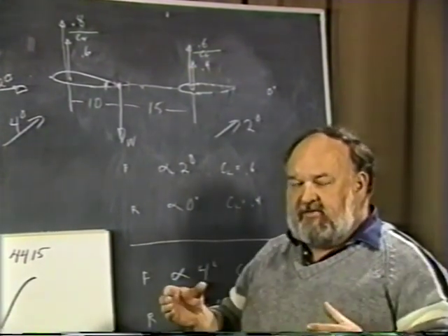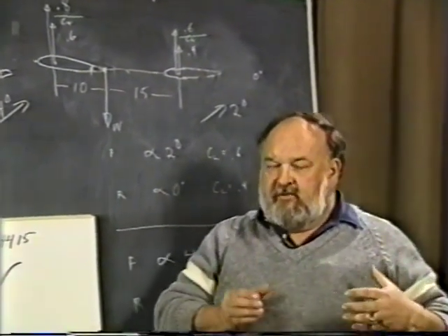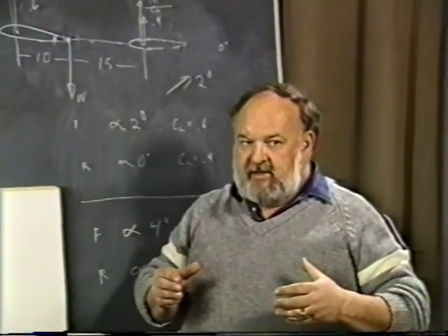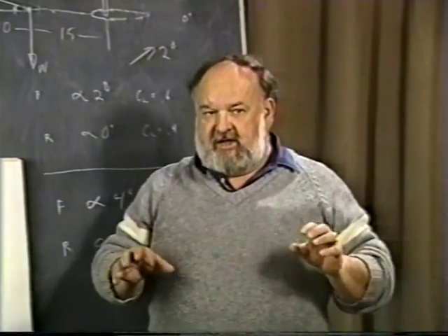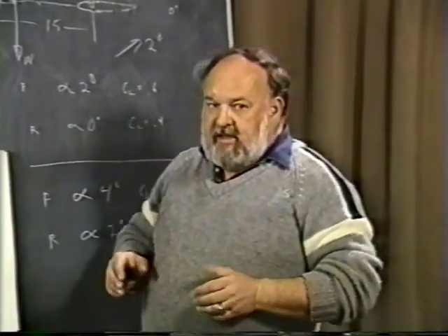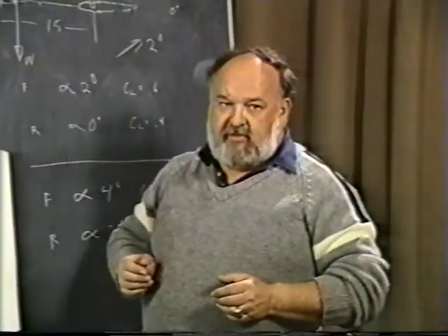You have the front surface, which must be producing lift. You have a rear surface, which must be at a lower incidence, lower angle of attack, so that when a gust condition comes, its change is greater percentage-wise than the change in the front. On a normal airplane, this is a large surface. This surface in the back here is relatively small.